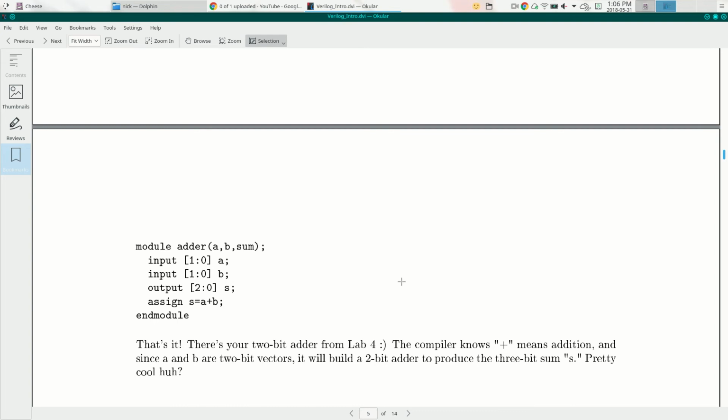So when you have the brackets and the inputs, when they're in the same line, it just means that it's already initializing the wire? It means it's a bus. It means A is not a single wire, it's actually 2 wires in this case. Okay, gotcha. And S is 3. And if I want to refer to them, I could do A bracket 0 or A bracket 1, because I started from 0.